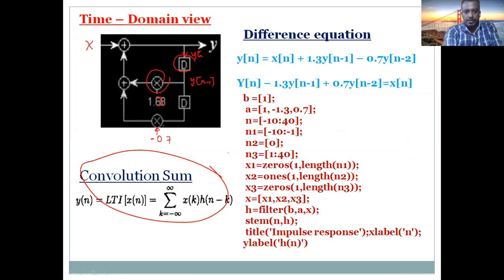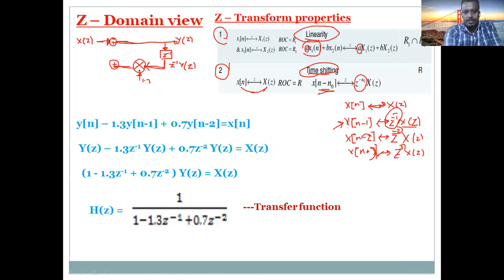Same thing for addition. In time domain, when you took addition, in Z domain also, same addition. Why? Again, because of the linearity property. Look here: when you have x1, X1 of z, x2, X2 of z, when you add these two signals together, in Z transform also addition. So this is the linearity property of Z transform.